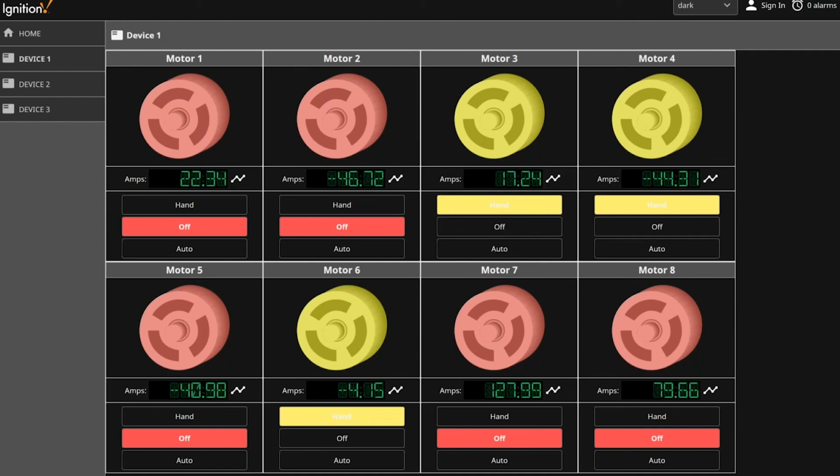What people do to get around that is you can have multiple UDTs that inherit other UDTs so that you can have a dynamic number, or you can just use a folder structure. So I could have a folder for devices, and then I've got instances of motors inside those folders. But also sometimes people will have additional tags in there, but they're disabled in some of them.